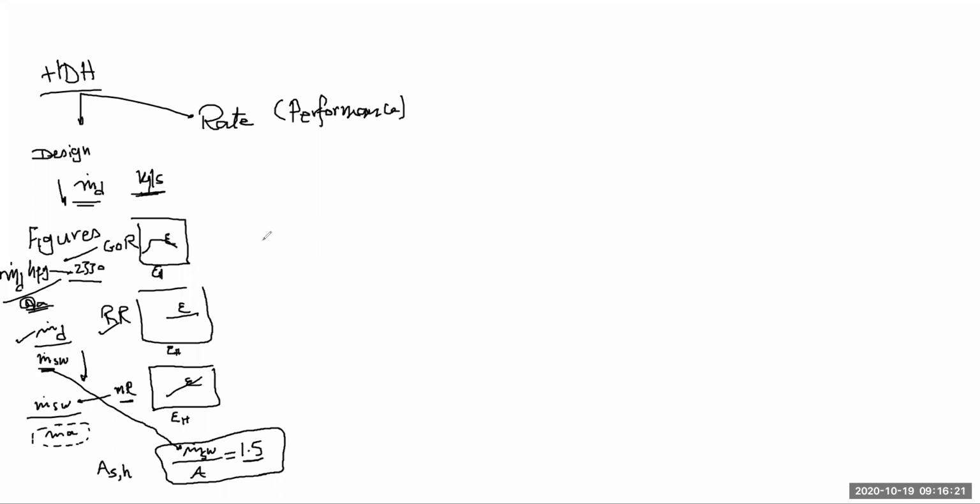And then we go to another figure that is going to give me the height of the packing material based on the maximum temperature, which basically, because these figures were made for a maximum temperature of 60, so in most of the cases, you'll be asked to deal with a maximum temperature of 60. If the maximum temperature of the system is different, then we have to provide you with the figures that are suitable for that. Then you calculate the height of the humidifier. Then there's another equation based on the overall heat transfer coefficient, which is given to you. You can calculate what is the surface area for the dehumidifier, whether it is based on water heating or air heating, and then you can get the value.